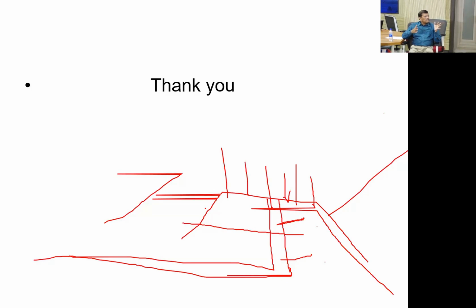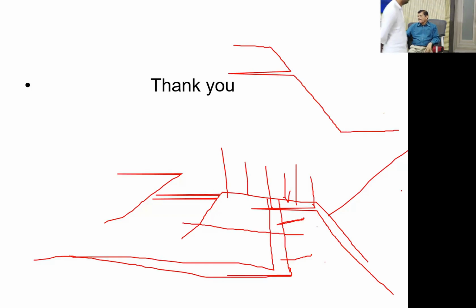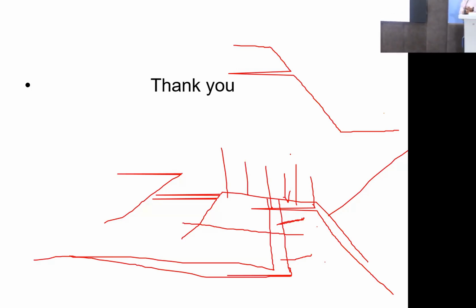Anything up to 3 to 1 is fine. If it is a steeper slope, you cannot put a liner there. Installation will be difficult. The liner width and length is 8 meters by 140 meters. They keep the bundle at the top and just roll it to the bottom. While stitching, they can easily stitch. And nowadays even thermal stitching is coming, so that's not a problem.